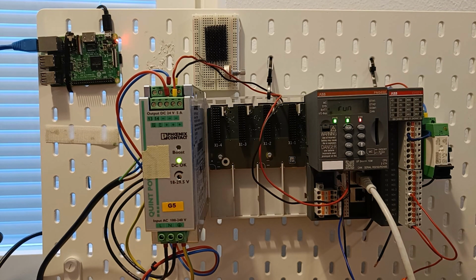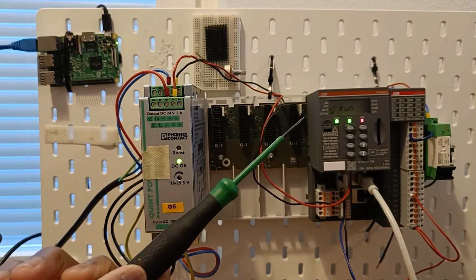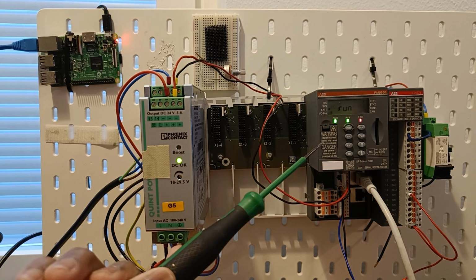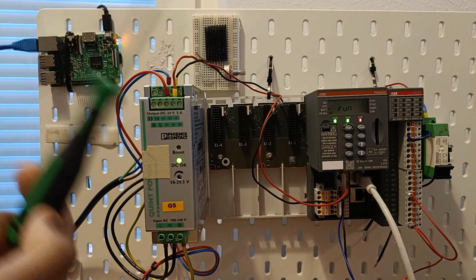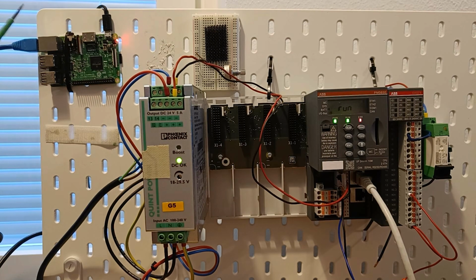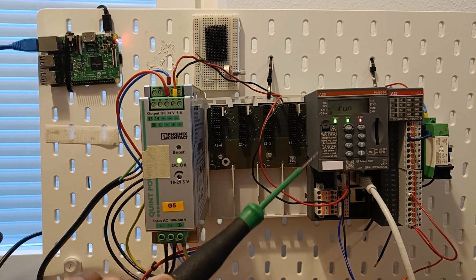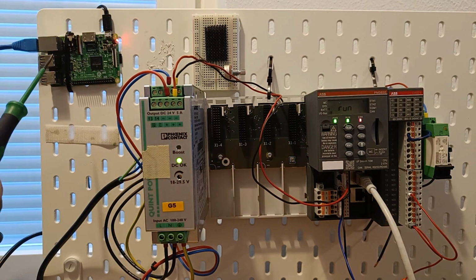So a little bit of the setup that I have here. I have my Raspberry Pi here, as you can see on top. It's a 3B. And on the bottom here, I have an ABB AC500 V3 controller. In this setup, we want our Raspberry Pi to be the Modbus RTU Master, and it will be reading data from the slave or server, which is this controller here. So the ABB controller is the Modbus RTU Server, and our Raspberry Pi will be the Modbus RTU Master.